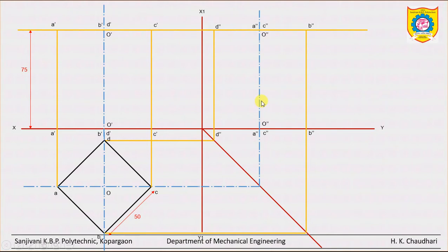Okay. Now we have to draw the horizontal prism. We know the size and the position also. So take half of the height of the vertical prism, 37.5. If it is not given, then we can assume that the axis of the horizontal prism intersects the vertical prism at half distance. We can assume this if not given, and if given, then directly measure.